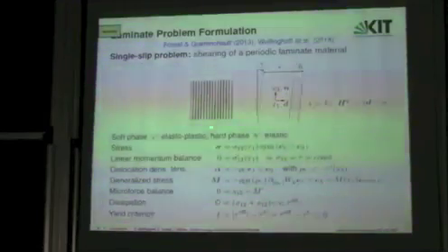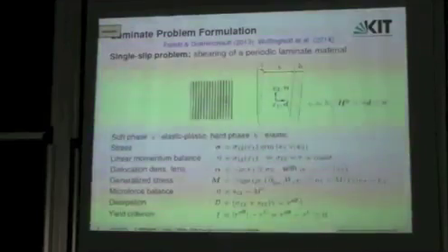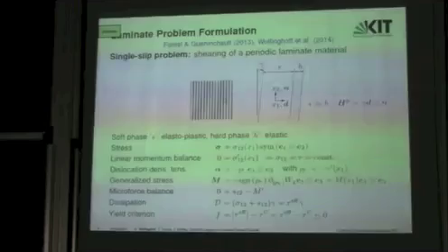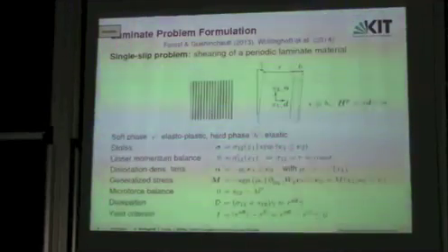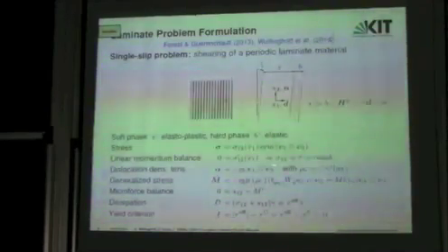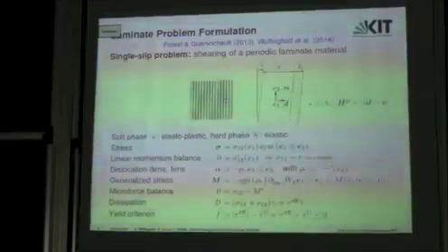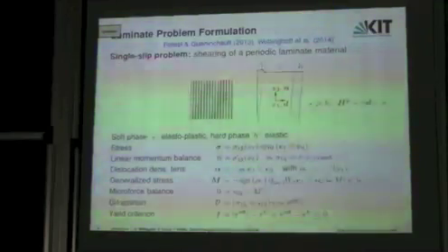Then the only stress component which does not vanish is the shear stress component, which can easily be shown by the linear momentum balance to be constant everywhere. So it's a very simple situation here. And it is also equal to the resolved shear stress in the slip system.